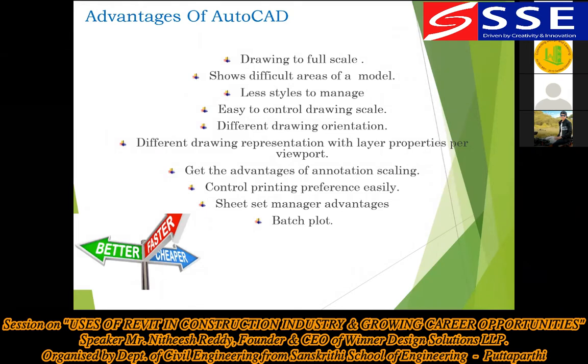So you can make it to full scale according to your adjustment. You can make scaled drawings, show difficult areas of modeling, fewer styles to manage, easy control of drawing scale, different drawing orientations, different drawing representations with layer properties and viewports, and get the advantages of annotation scaling, control printing preferences easily, sheet set manager, and batch plot. Okay, if you have drawn, like you have created a layout.